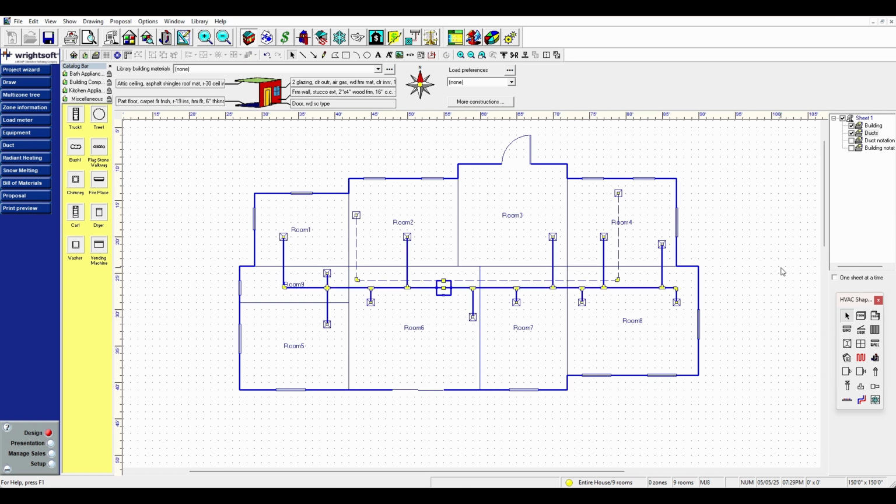We will get into the details more, but the reason why that's important is for a number of reasons. Like I said, number one, it means the return grill is going to have to be really large. That could be a little challenging to work with, and the duct for it will have to be large. But also, there are limits on the speed of the air inside the ducts, okay?